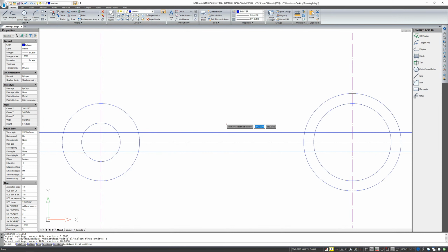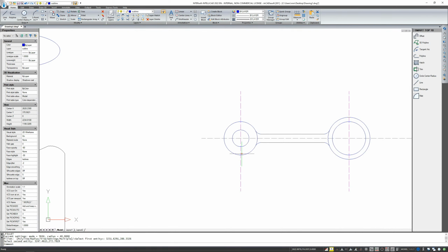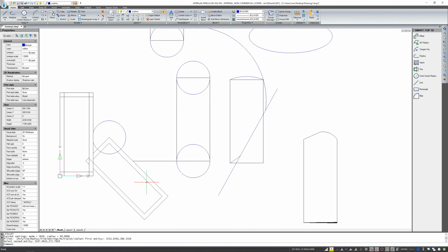And here I'm showing you the line and the circle. I'll repeat this operation. Now it is shown at the bottom that the radius is 40, so I don't have to enter these settings again. I approve and do the same on the other side. I could make one element and then choose the mirror option, but maybe I'll show you the mirror option on another example. Of course, you can also show Fillet, for example, straight elements and chamfer in the same way.